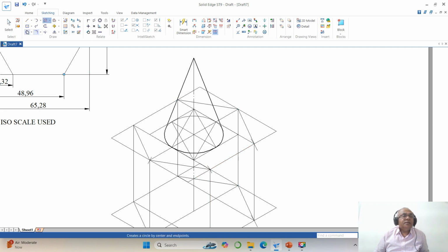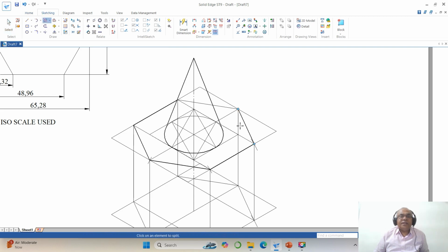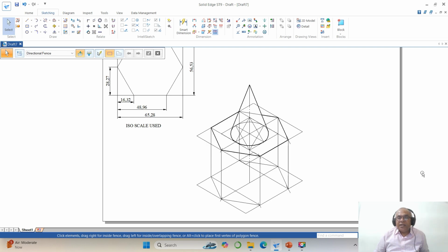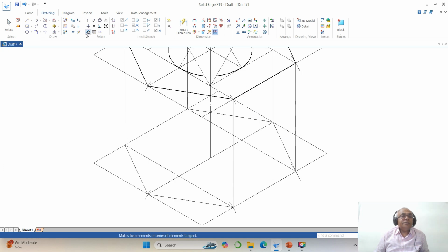split this till here, go to sketch, select this top surface of the hexagon, okay, make it 0.5, then you go to split this line till here. Now you go to select this and make it 0.5, okay. So this is the surface. Now similarly at the bottom surface also you need to do it. So how to do that?